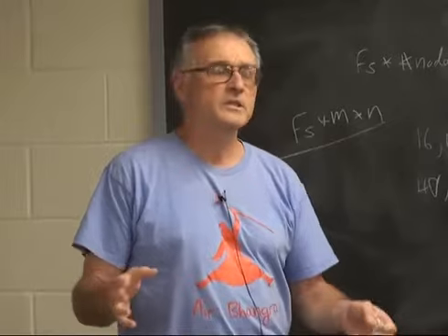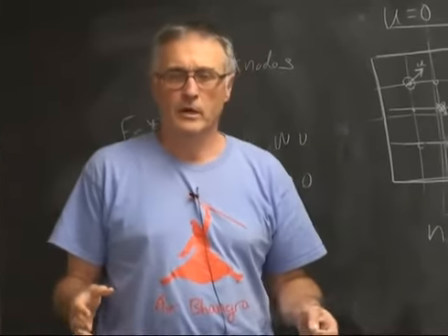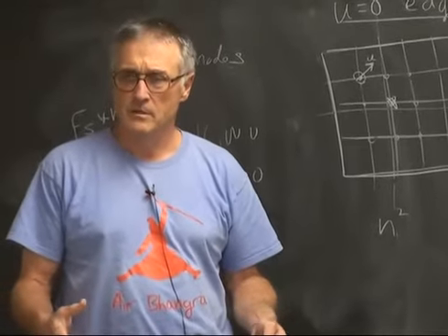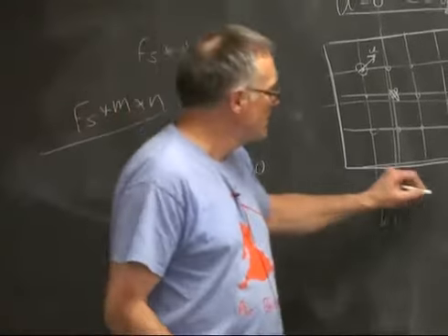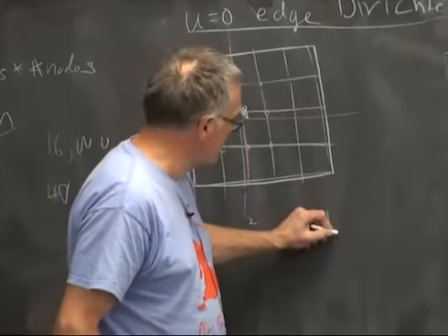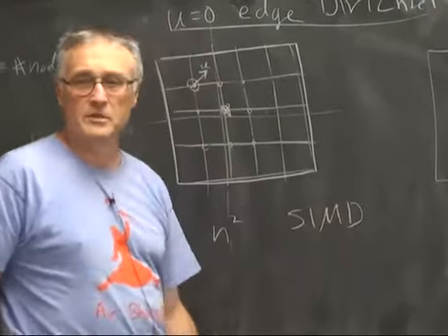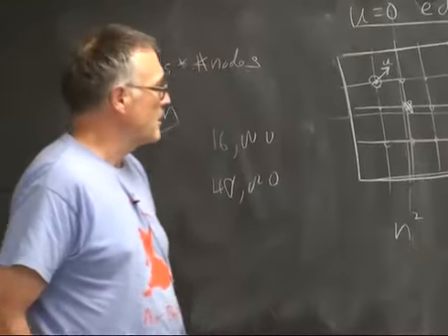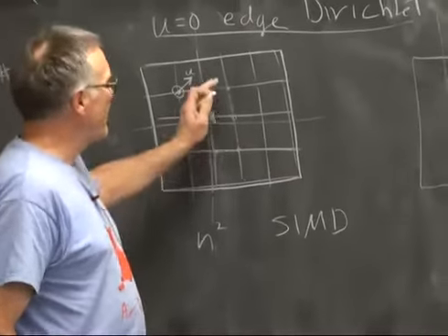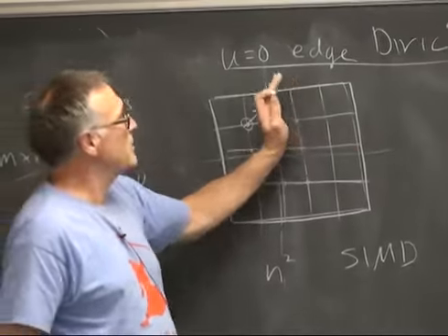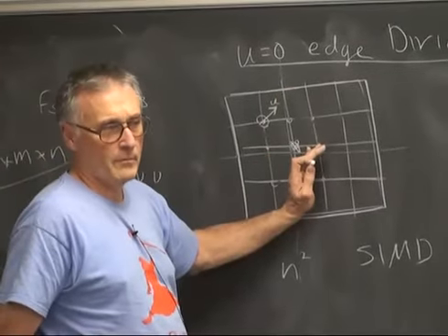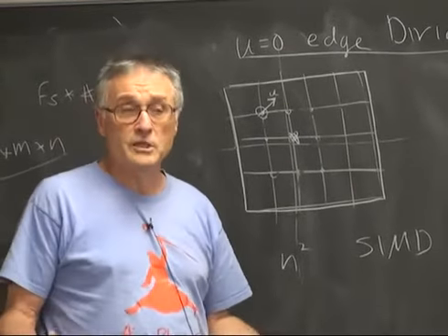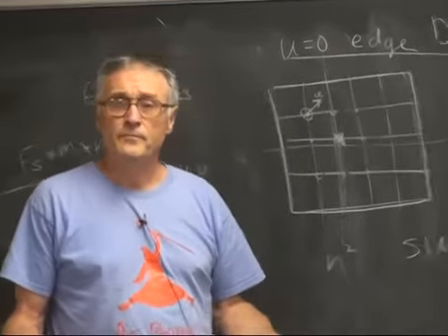So, the first design decision is, are we going to go with lots of lightweight processors, so-called single instruction, multiple data, SIMD computer, or are we going to do a heavyweight processor with just a few of them? You have to do one or the other because you're limited to a total number of logic elements on the chip.